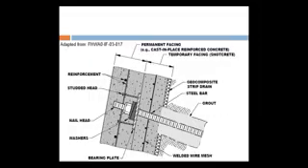Now again, at the joint, how it looks: reinforcement, shotcrete head, you can see the bolt, nail head, washers, geocomposite strips, drain, steel bars, grout, welded mesh. So temporary facing, permanent facing, you can see over there.